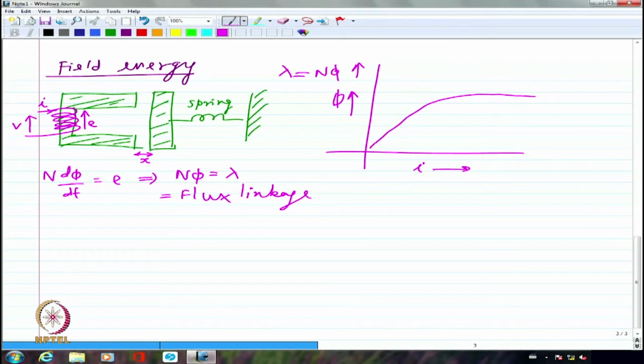If I have a smaller air gap, I am going to have more and more non-linear characteristics because of the iron coming into the picture, whose reluctance is dominating. Right? So if the air gap is smaller, I am going to have highly non-linear magnetization characteristics like what we saw in the case of the transformer.